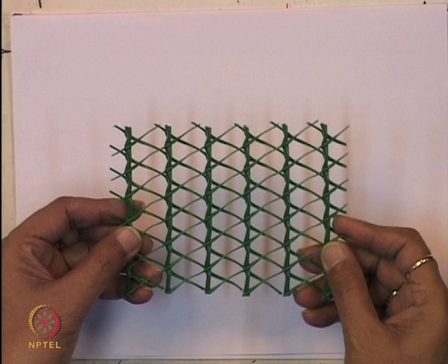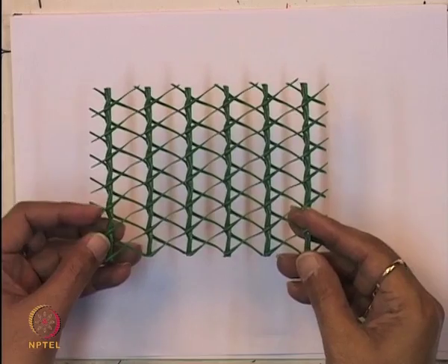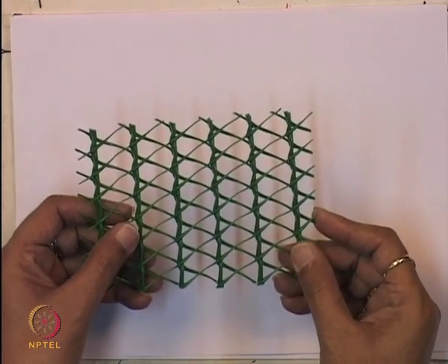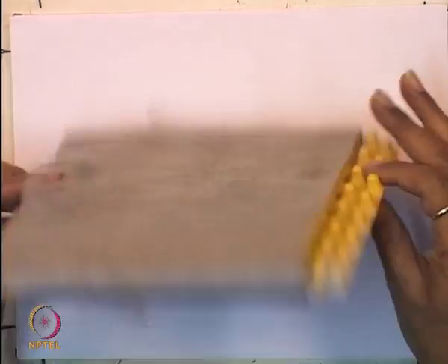I am just showing you that triaxial flow net. You can see this is the triaxial flow geonet. So, you can use the triaxial flow geonet, or you can use any geocomposite sheet drain, like this also you can use. So, depending upon the type of flow, you can use this prefabricated material.